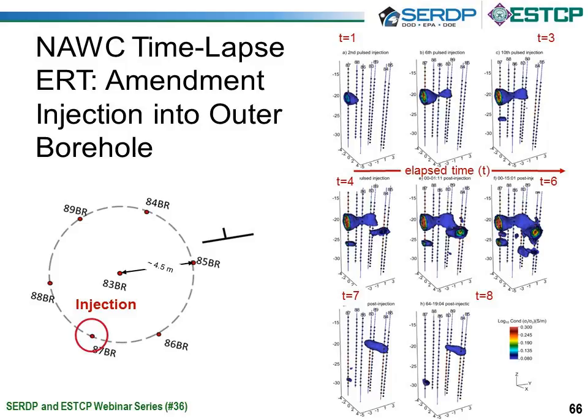So in this study, we were able to really monitor the movement of a tracer without affecting the hydraulic gradient, because we literally just injected and then did our ERT imaging at a scale that we wouldn't have been able to achieve just looking at borehole sampling alone.